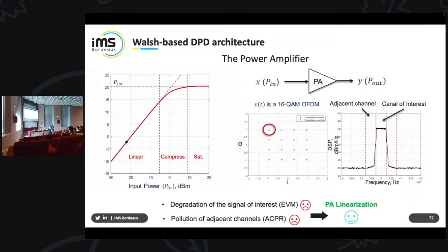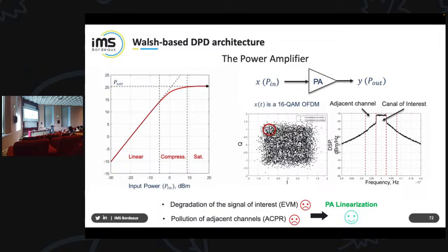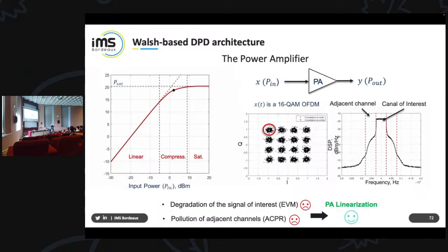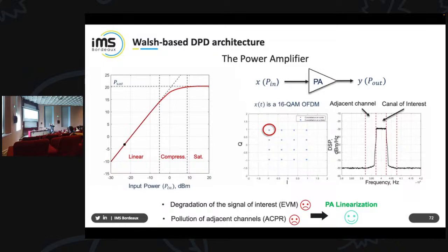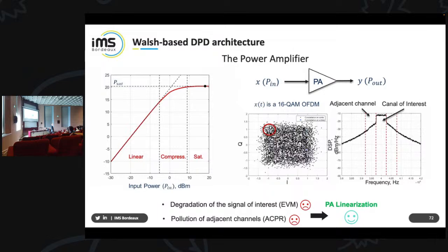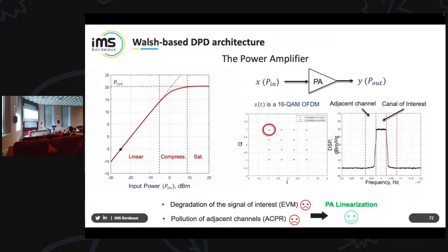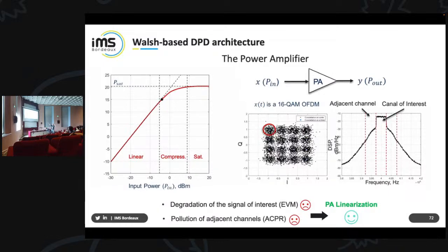What is saturation? It's when your sine wave will stop being amplified and it will be more and more like a square wave, kept at the top. When you cut a sine wave with just pure harmonics, you are more like a square wave, so other harmonics will come. And you are going to pollute your spectrum. We don't want that. We want to avoid it.